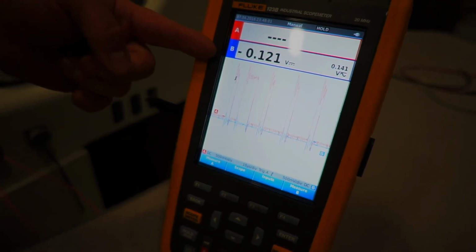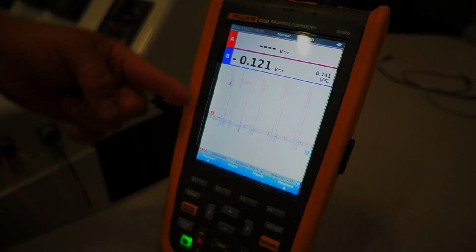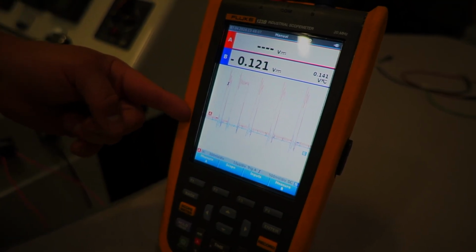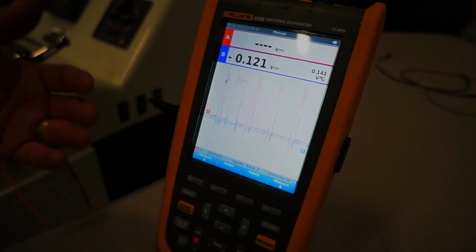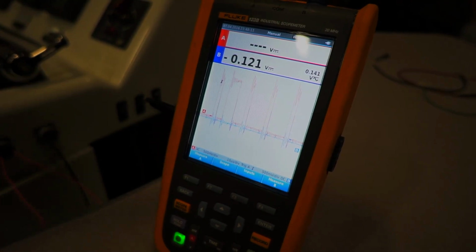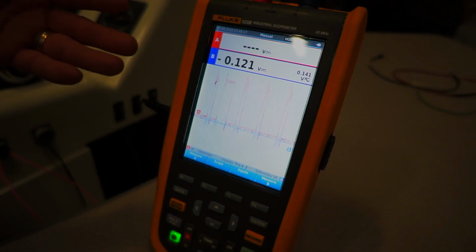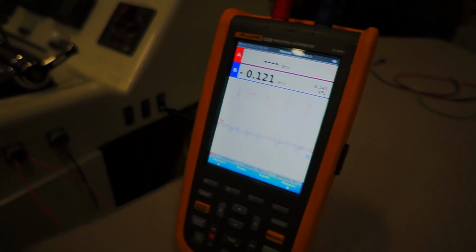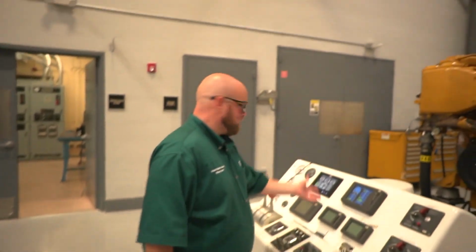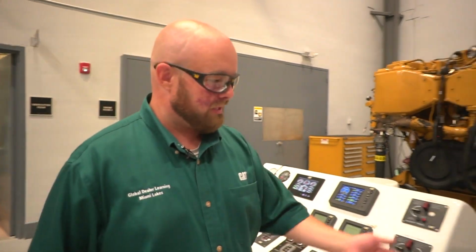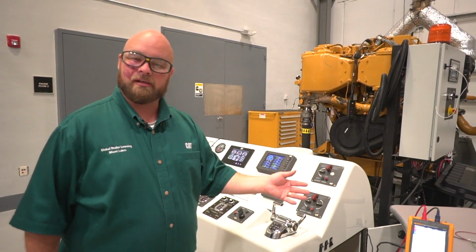When the red line, channel A, that's the CAN positive, shoots up, the CAN negative, though, is grounded out. It stays low, but the differential voltage in this case is still around 2 volts. So in this case, you notice you don't hear anything going off and beeping either. We've shorted out the CAN negative to ground, but yet everybody's still happy. Everybody's still communicating. Our signal doesn't look like what we expect it to, right?